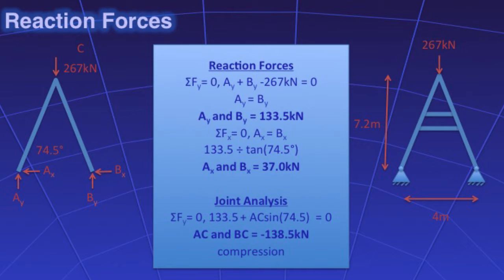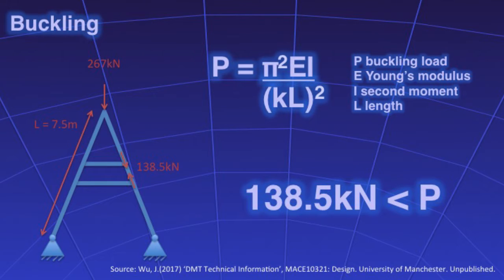The engineers must ensure that the frame does not buckle by making sure the load applied is less than the maximum buckling load. Material selection and cross-sectional area can increase the maximum allowable loading. The team chose steel I-section beams due to the cross-sectional area being greater at the farthest point away from its neutral axis, giving it a higher second moment than other cross-sectional shapes.